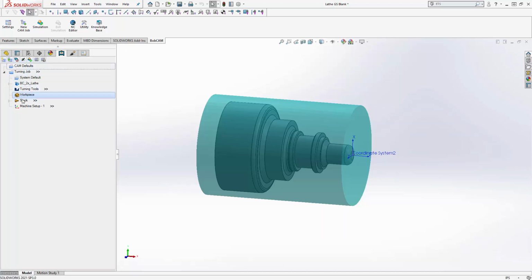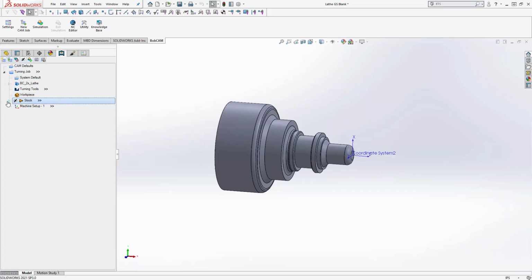And then I'm just going to right click on the word stock and say blank unblank. Now when you're going in here, you still have your full material library. So you could set up your materials. But when you're setting up normal turning tools like CNMGs and VNMGs, it's not actually using those tools for the feeds and speeds. You're still going to enter in your constant surface speed. When you do your drilling, it will actually calculate feeds and speeds for you.